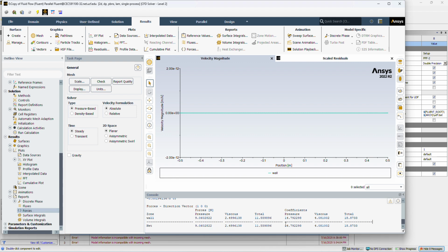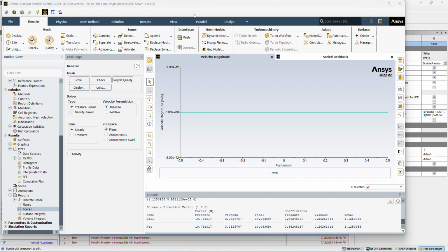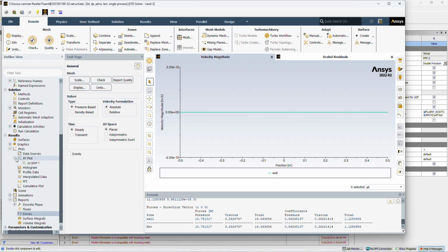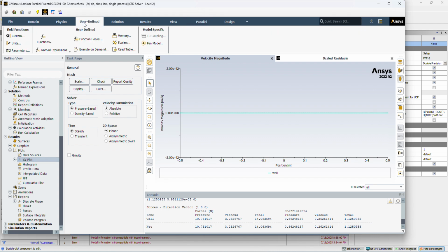And then we find, yeah, these are actually quite high. Yep, there we go. And we should be able to find that our coefficient of pressure should be fairly close to 1. It's around 0.8624. And this total is 1.125. So that is what we get from this. We got our plot, and then we can go on to our velocity fields, or the streamline fields.